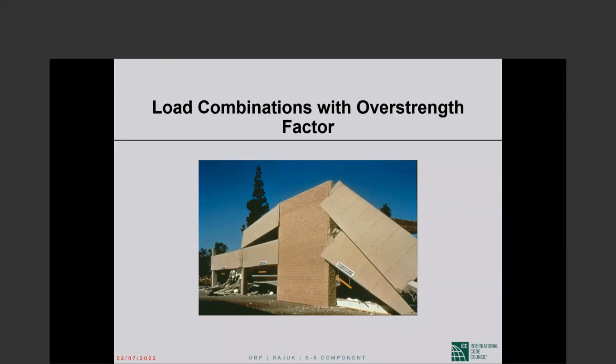And the question immediately arose, how come the rest of the structure is doing so badly and the shear wall is so much better off? And the answer that emerged pretty quickly is that the shear walls didn't have to do anything during the earthquake. And when you don't have to do anything, it's easy to look good.